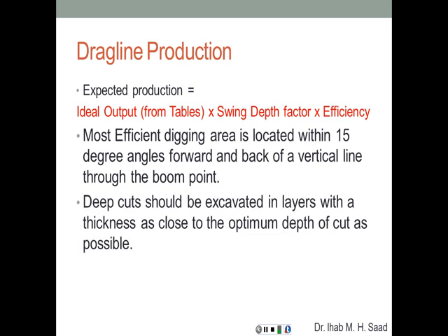Deep cuts should be excavated in layers with a thickness as close to the optimum depth of cut as possible. So you can do it in different layers. Once you finish one, you move to the following layer.